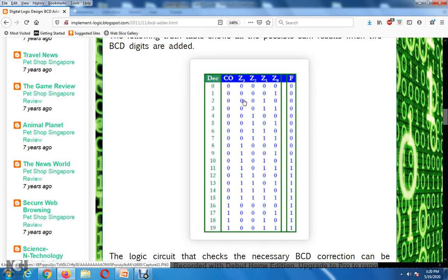Either your digit in the 4-bit field Z3 through Z0 is invalid, or you got an overflow in the first stage. So we see an OR between these two things, and we can break them down separately. So we derive an equation that lets us correct in the range 10 through 15, and then we OR that with the carry out.